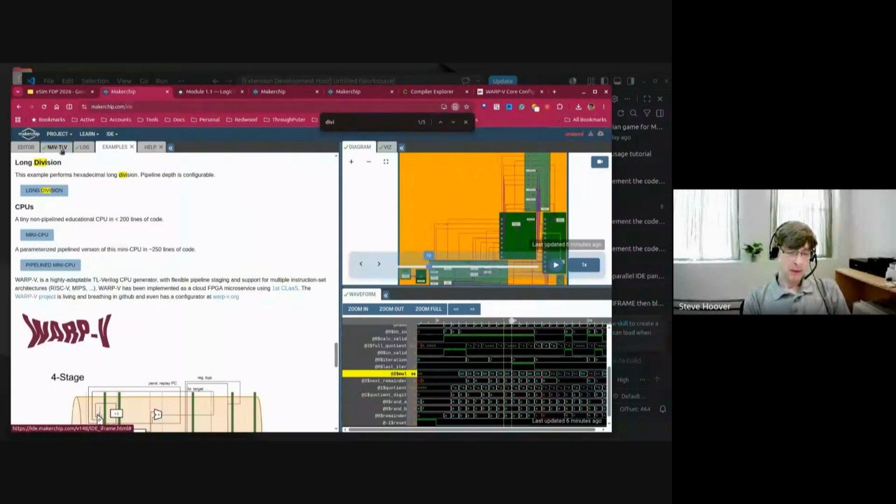One of the main limiters there is that the technology has evolved around C++. C++ is not a hardware language. It did not have hardware in mind at all when it came about. It provides a foundation for SystemC, which uses it to model hardware. But there is legacy baggage associated with the C++ heritage of high-level synthesis.